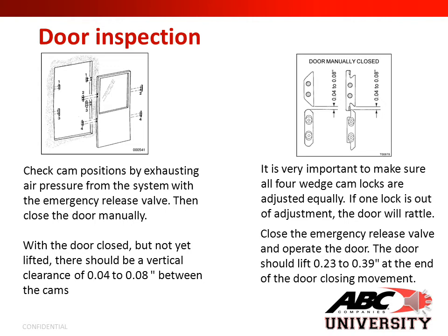If one lock is out of adjustment, the door will rattle. Close the emergency release valve and operate the door. The door should lift 0.23 to 0.39 of an inch at the end of the door closing movement.